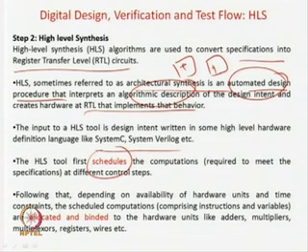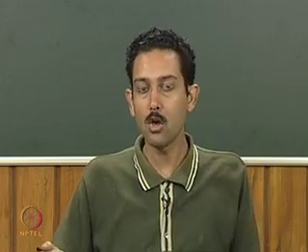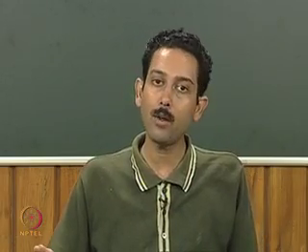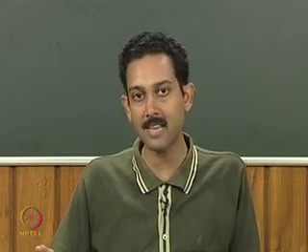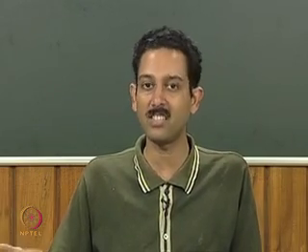Say you have to add A plus B and C plus D. These are two adders, so there are two operations you have to do. You can schedule both of them in one step, or you can schedule A plus B in the first stage and C plus D in the second stage. This is actually called scheduling. What operations you schedule in what step is called scheduling.